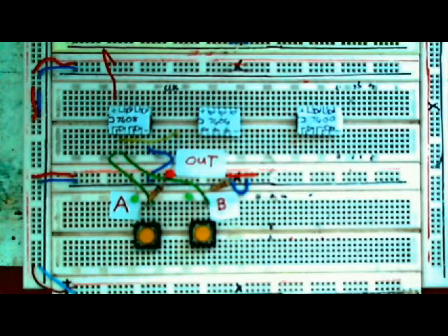In digital electronics, there can be only one of two possible binary states for both the inputs and outputs of logic gates. Basically, they can be either 1 or 0. 1 being a high signal, usually plus 5 volts or 3.3 volts, 0 being a low signal, 0 volts. The tolerance for the IC will be found in the datasheet for that IC. Typically, they will start switching from anything above 0.7 volts.